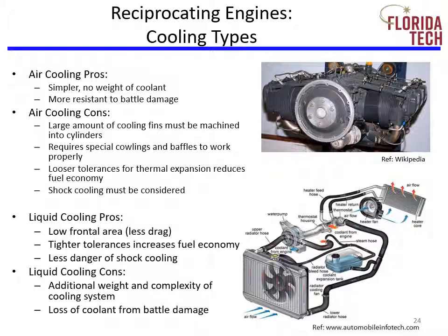This is where rapid cooling arises on descent from altitude. In this condition, less power is demanded of the engine because the throttle is back, so it's developing much less heat. In the descent, the airplane's airspeed increases, simultaneously increasing the cooling rate of the engine. As metals expand and contract under this temperature change, dimensional changes in the engine may exceed tolerance limits.